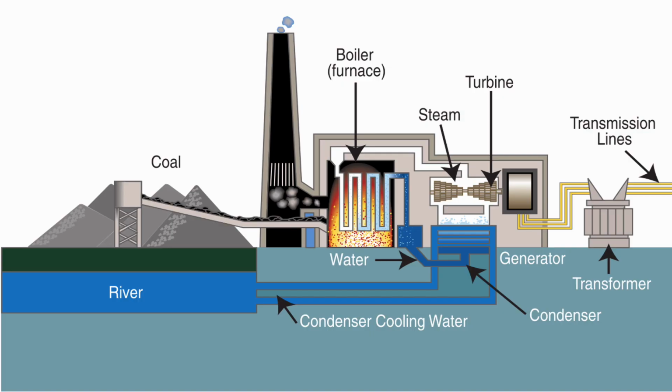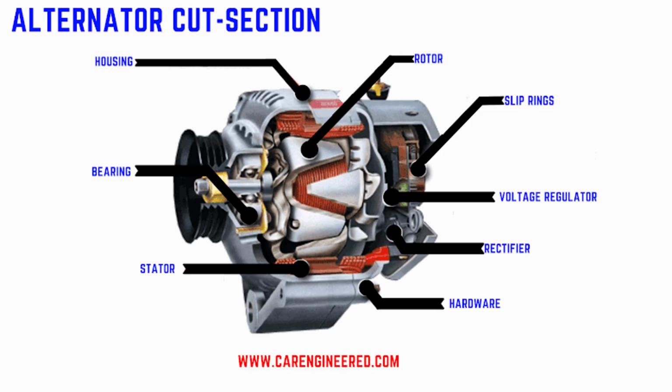In an AC generator, mechanical energy is converted into electrical energy. This process involves rotating a magnet, the rotor, inside a set of windings, the stator. The rotating magnetic field induces a voltage in the stator, producing a sine wave. It can be expressed in the following form.